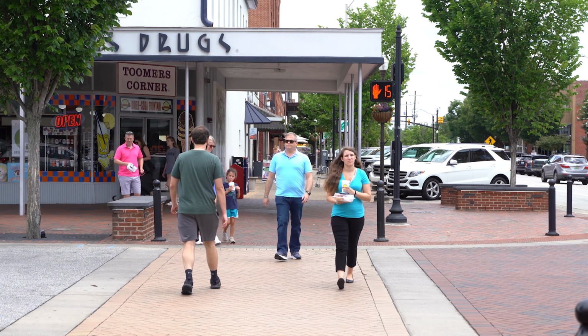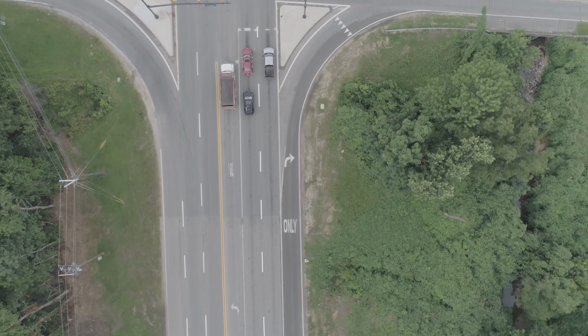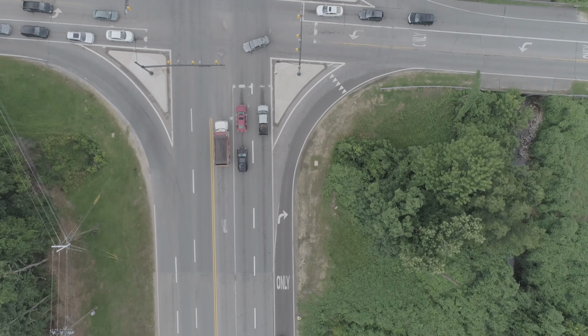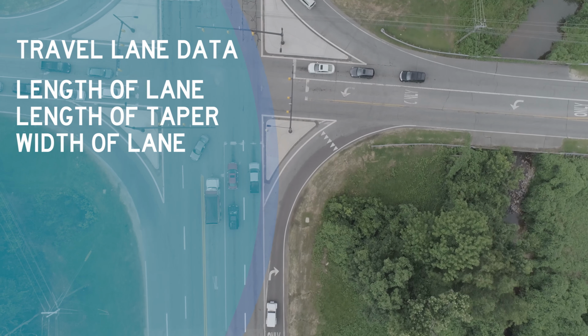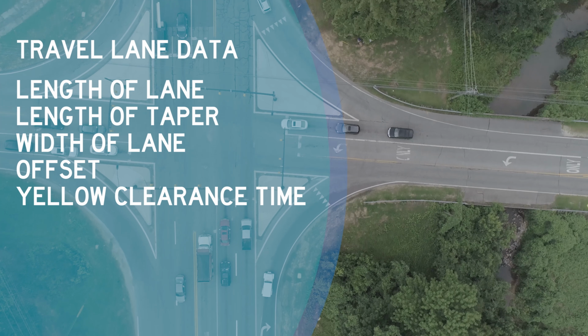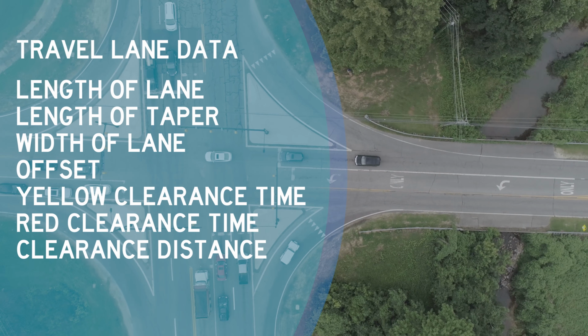Adding or editing travel lanes, such as left, through, shared, and right, will require field data collection. We will need things such as the length of the lane, the length of the taper, the width of the lane, if the lane is offset, the yellow clearance time, the red clearance time, and clearance distance.